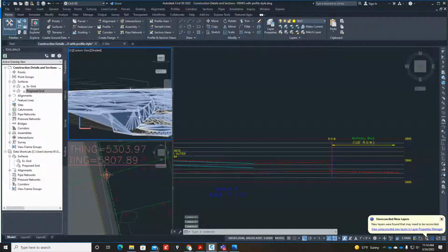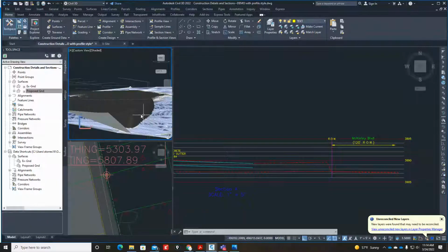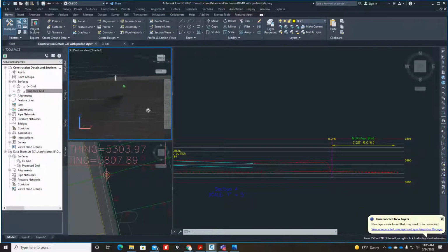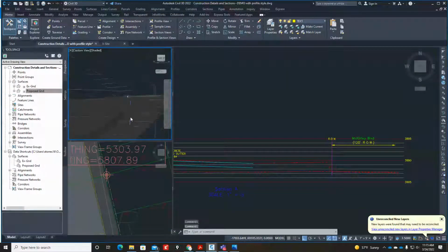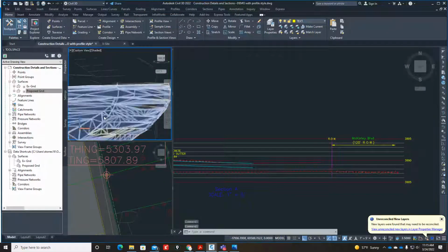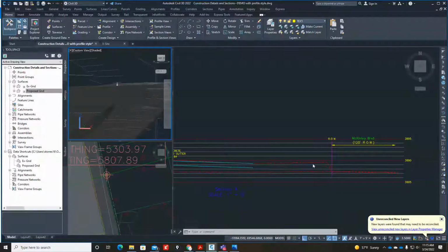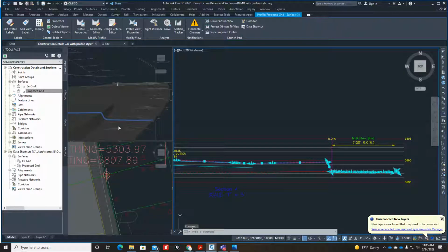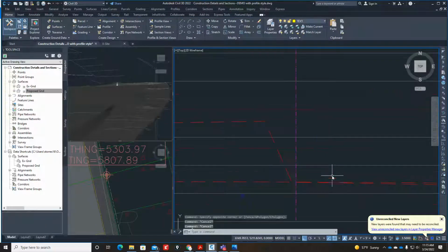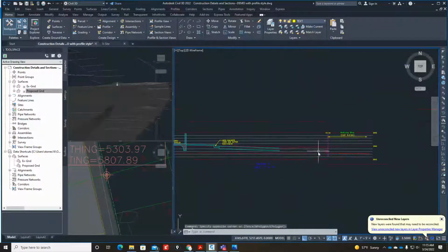But once again, you can kind of see that this vertical difference is a lot bigger. If you were to walk off from here and come down here, that's a good 7 or 8 feet of drop. You might hurt yourself if you're not careful. But so that's what we need to draw. So we need to draw in a new rock wall at that point. Right in there, you can kind of see where it's highlighted. That's where we need to draw in a new rock wall, and then the paving coming up to that elevation. Okay. So this will be the other side of the elevation, which is at this point, that's where we're going to put in our new sidewalk and curb. So let's go ahead and draw that next.